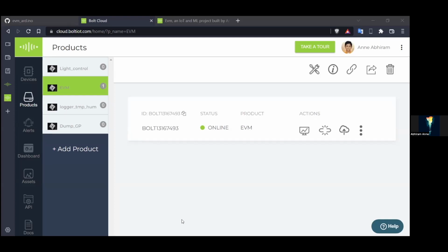When you connect a switch, you employ a pull-up resistor. What is the purpose of this pull-up resistor? It helps the Arduino board understand whether the switch has been pressed or not. When you press the switch, it is logic 0, and when you release the switch, it is high, logic level 1. Now you might have understood that I've not used any external resistor because the Atmega chip has an internal resistor. Using the code, you can access that internal resistor. If you access the link, you will find this pull-up resistor, INPUT_PULLUP.